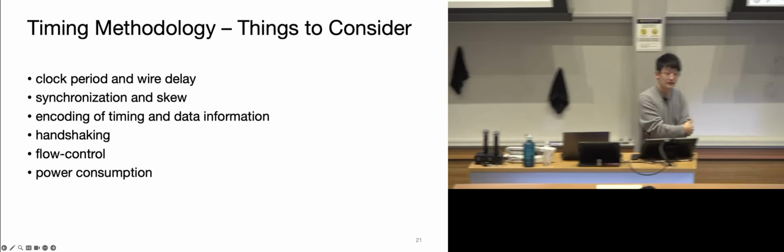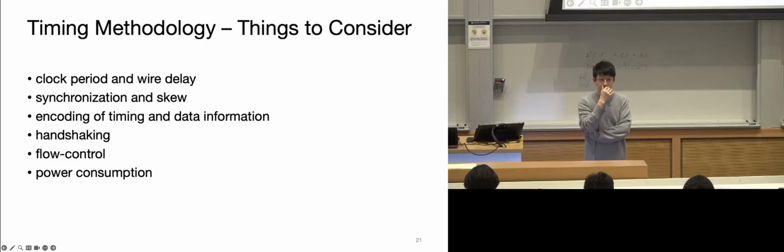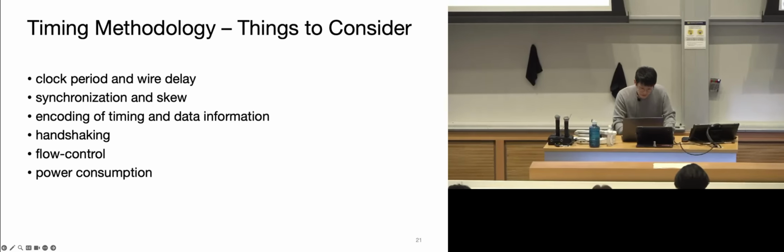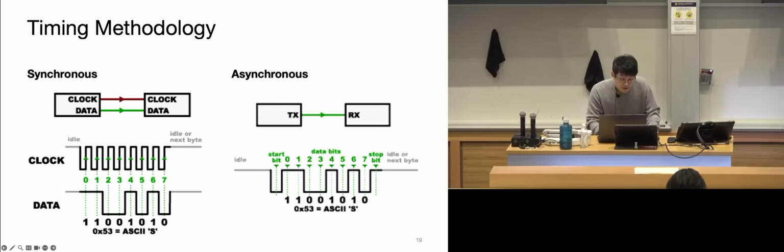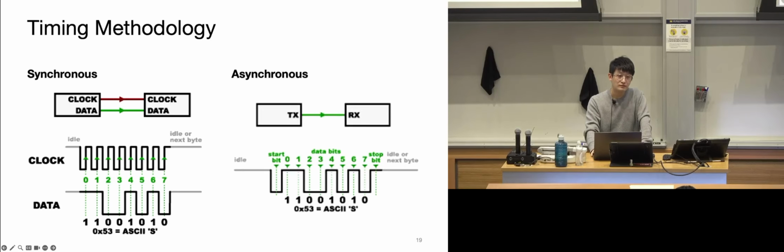Yeah. And I had a similar question. So with the synchronous bus, when you're sending the clock and the data over the wire, the clock signal could reach later than it was sent, right? It's possible, yeah. Would the receiver just lock it in when it receives the rising clock edge? The receiver will use the received clock edges to decide, yeah. Okay, so hopefully they're all delayed by the same amount, so it'll work the same. Yes, yeah, chances are they use the same wire.